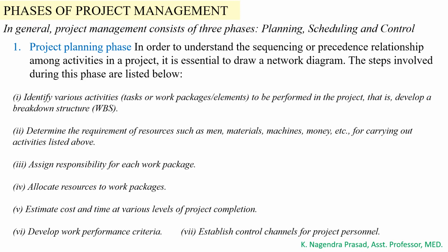Here also, in the planning phase, first we have to identify the various activities to be performed in the project, that is, develop a work breakdown structure. After identifying all the activities, we have to determine the resource requirements for each activity. For example, for foundation work, we have to identify how much money is required for the foundation stage.